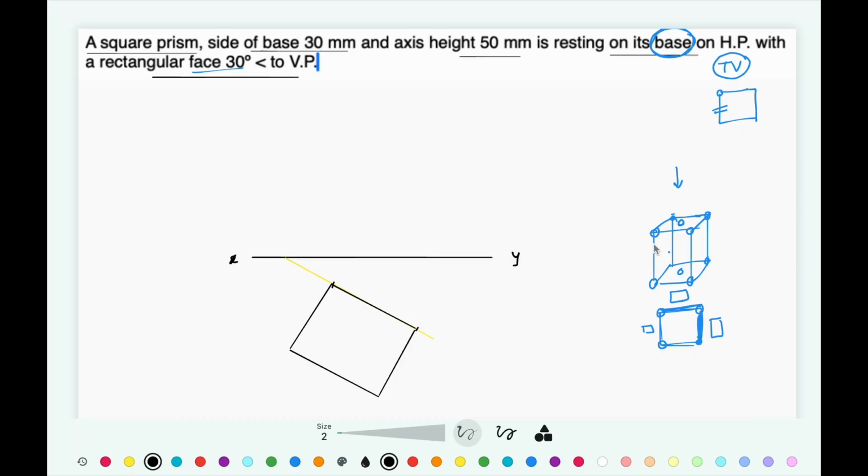Now when you have drawn this top view, there are two faces, one at the top, one at the bottom. So let's say you provided the names ABCD to this top face and 1 2 3 4 to this bottom face. Okay, so for every corner we need to provide two names.